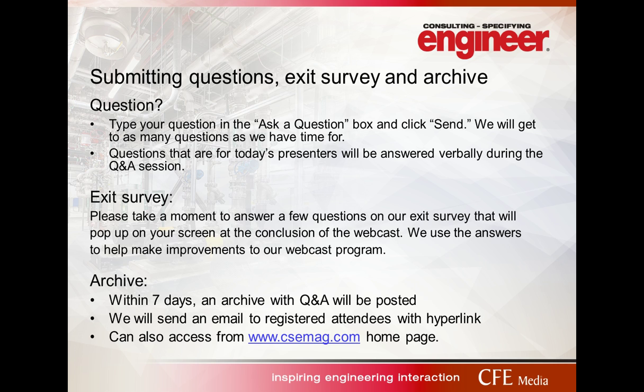If you have a room like a clean utility room that needs to stay positive, but it's a small load to begin with, you might just make that specific room constant volume and let the return air modulate with the system so that the room always stays positive. It'll change its positive and negative, but it'll always at least be positive. In a room that needs to be negative, like an isolation room, you would either make those constant volume or have those supply and return connections tracked as well. We found that the high performance type valves perform a lot better than a blade damper valve in those cases. That's what I would say about that.